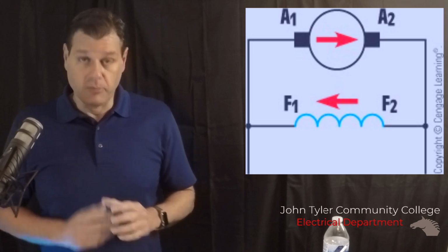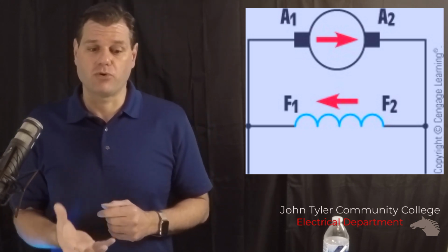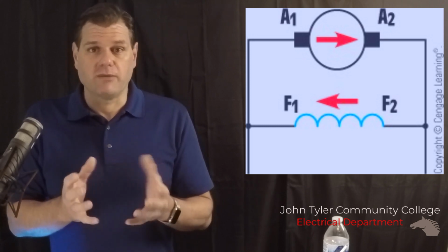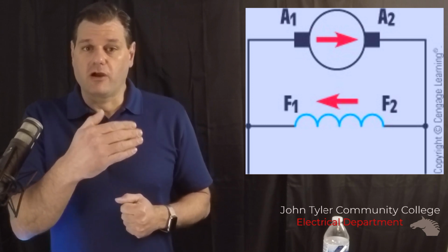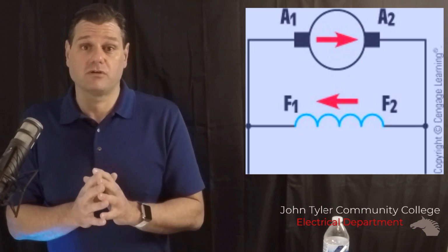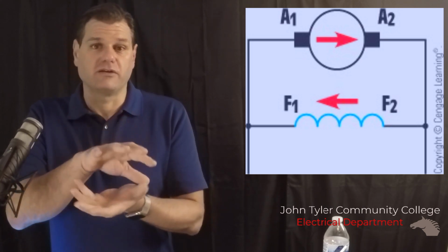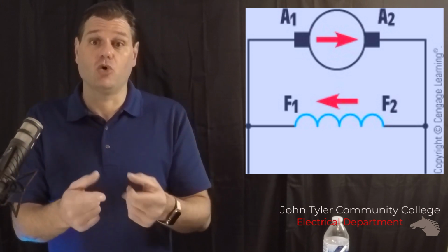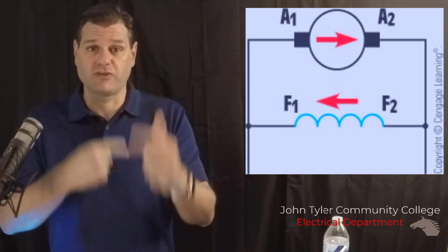Okay. Well, up to this point, we're talking about stuff that is called self-excited. So self-excited motors or generators, because they're both the same physically, they are creating their own exciter, essentially. Right? So self-excited is as the armature is rotated, it is allowed to cut through the flux. The flux is then producing voltage. The voltage is feeding its own coils. Its own coils are producing magnetic flux, which is cutting through again. It's self-exciting the same circle.